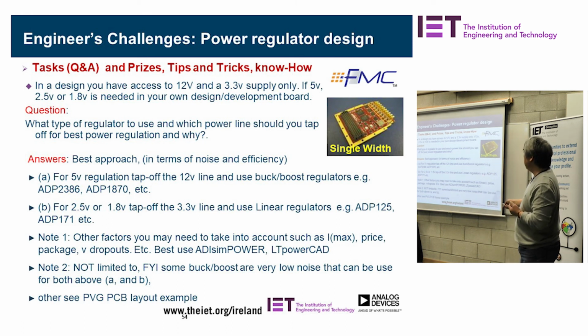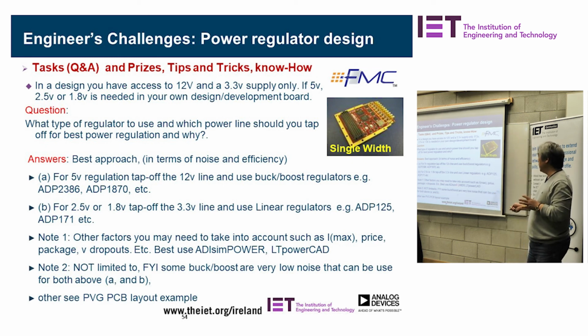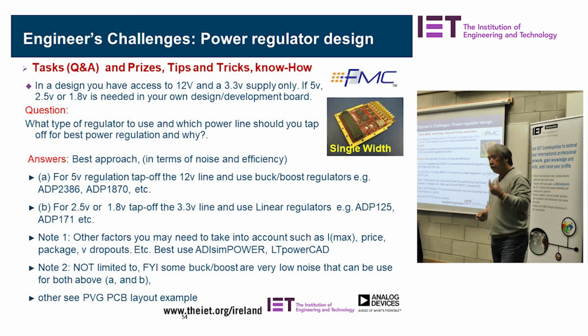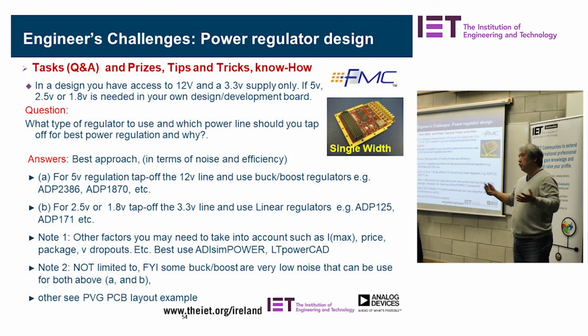So this is the power regulator. But keep in mind, this is a rule of thumb. Some switching regulators are very low noise. Analog Devices has very low noise switching regulators, which they call silent switchers. You pay a premium for those silent switchers. But the other question is, do you need it?